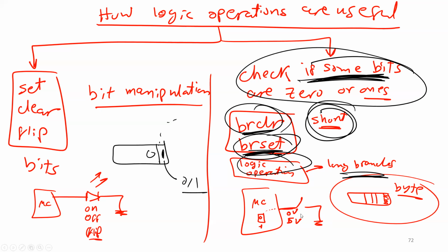This is what I'm explaining here in that figure. We have an external pin. This pin is connected to a switch, and somehow the hardware connects this pin to 1 bit in a byte. Then if the switch is open or closed, I'm going to put here 0 volt or 5 volt, and here in the software, you will find logic 0 or logic 1.